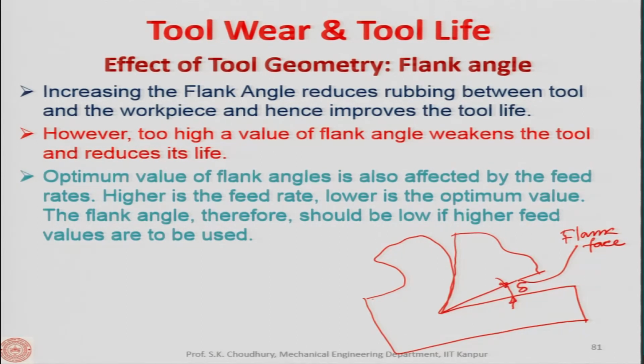Flank angle we designate by delta, all right. Now, if we increase the flank angle, again that rubbing will be less, because this flank face will be cleared and it will be safe, it will not anymore rub with the finished surface.